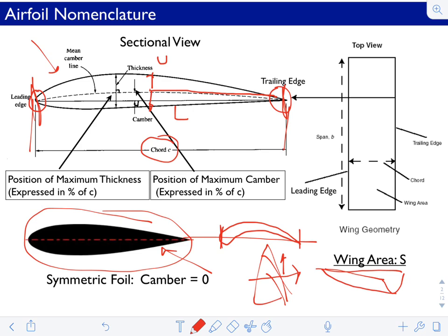This is a side view of the hull. The keel sticks down like this and often has a counterweight, which is counteracting the buoyancy of the boat. That thing right here is known as the keel, and that actually creates a side force that opposes the side force generated by the sails. In fact, they're in equilibrium. It is a lifting surface by definition, and over time, with the development of sailboats, things have progressed where they started using better and more efficient sections compared to, say, what the Pilgrims had, or even prior to that, that enabled sailboats to sail more efficiently.